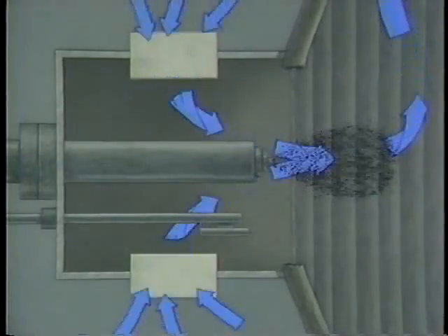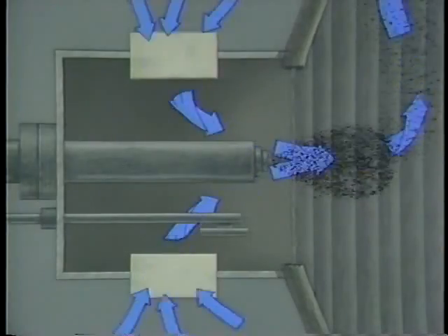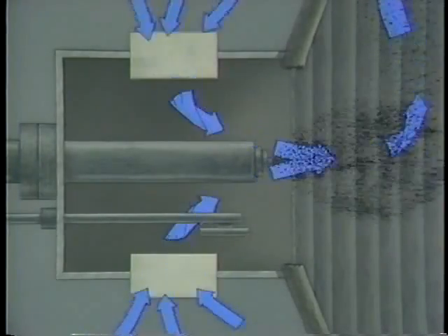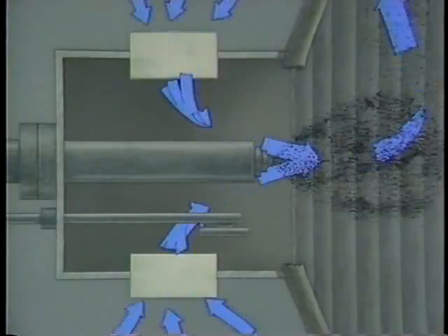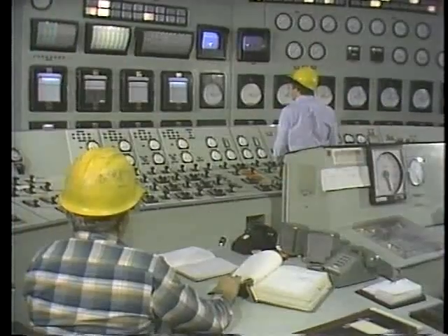The air and fuel form a combustible mixture. The mixture accumulates in the boiler as more fuel and air are supplied. If the igniter suddenly begins sparking, it will ignite this abnormally large mixture. The result is an explosion. The same thing can happen if a combustible mixture is present in the boiler prior to startup, and an operator sparks igniters without first purging the boiler.